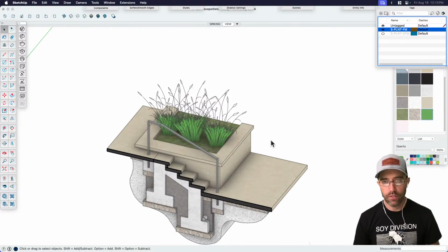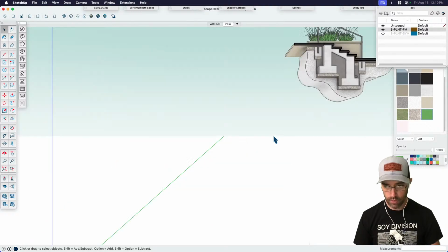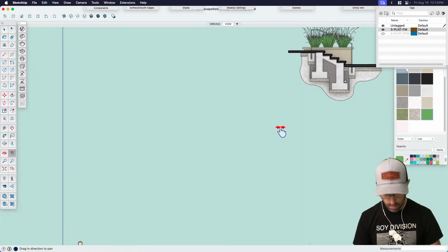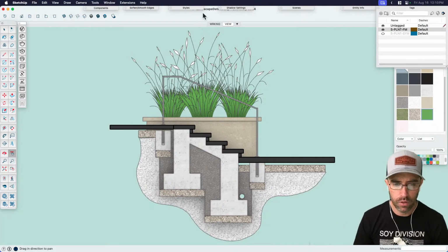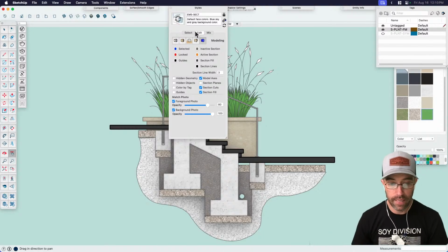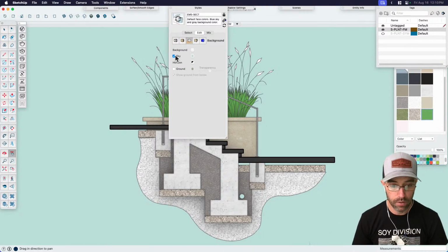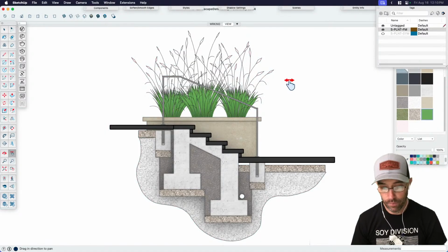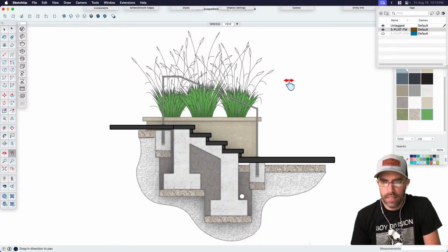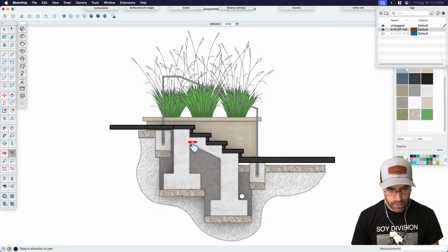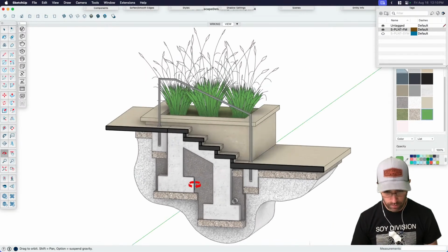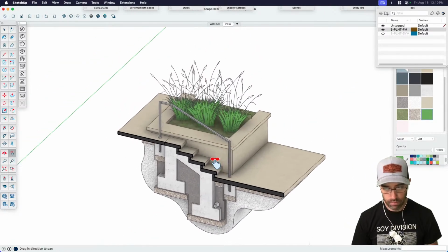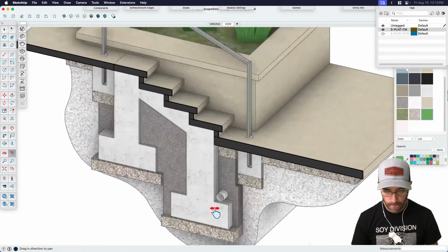So if I switch that around, you can see now I have that like this. So if I wanted to view this, shift to parallel projection and to elevation view. There we go. Speaking of elevation view, before we go to layout, I should probably come over here and turn my styles. I don't have to do this because I could override this in layout, but what I want to do is probably turn the sky off. And then there you go. So that's our detail. This is what it would look like if we just left it as a standard 2D detail. But of course, we went through all this trouble, so we're going to want to show it maybe a couple different ways.